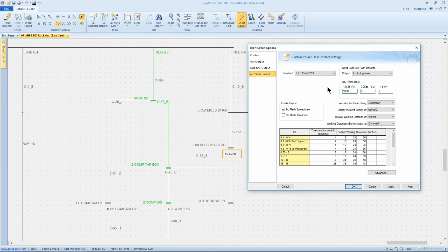Now the other thing that's worth noting is that with the new standard, you want to use the integrated method because there's a recognition of the fact that over time the fault current could actually decline for one reason or another, either loads dropping off or motor contribution declining. So on large faults or long faults, the integrated method will end up providing some relief.